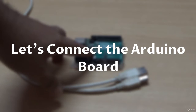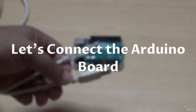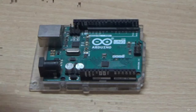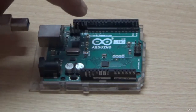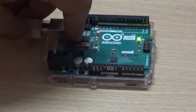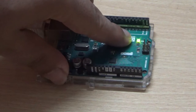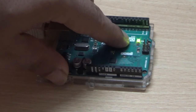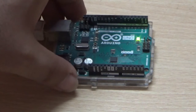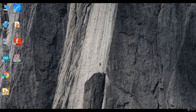So let me show you the process of how we connect the Arduino board. This is my Arduino board. Now I am connecting the USB cable. See, the board gets its power. The green LED is on. Now I'll show you how this board gets a COM port in my computer. As I have already connected my Arduino board, now I'll show you how to check your COM port.